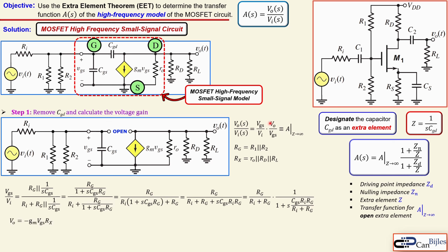The next one is about the VO and the VGS. Well, I see here the VO, which is our output voltage in the Laplace domain, is this current with opposite sign, so minus GM VGS, times the parallel combination of these three components, which are actually given as Rx. That's actually what you see here. So minus GM VGS, everything in the Laplace domain, times Rx. That's why we have, by the way, capital letters. If I now divide left and right hand side by the VGS, I have the expression I am actually looking for. So I have now minus GM Rx.